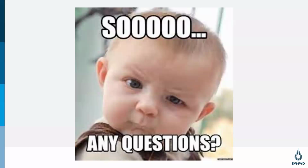But if we see a DMA that went from 97, 98, 99, all of a sudden down to 70, 75, 78, we're going to go out and look for a leak or an issue, or is it a data issue? There's so much data that comes in on a daily basis. It's almost hard to look at it. Well, it is hard to look at it all.